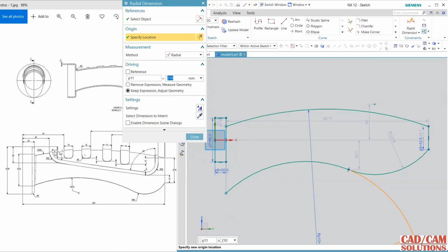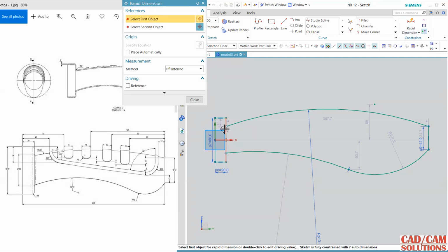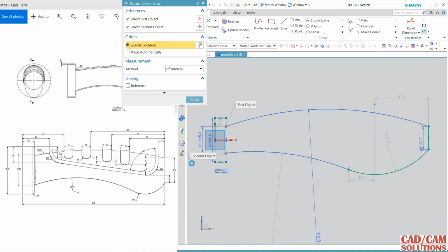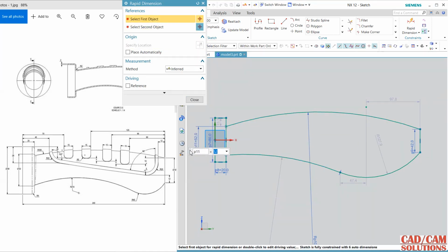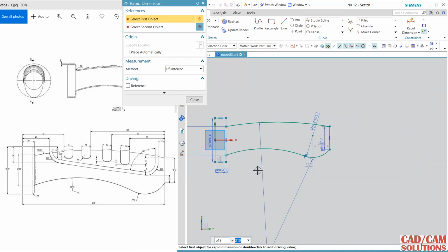It is out, so undo it and close. First I'm going to define the distance between these 2 points, so first point and second point, and the distance is 52 dia. Okay, now this radius is 40 radius, and this one is 210, and this total length is this 10 from this to end of this gap is 240.